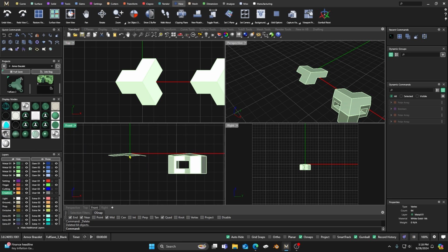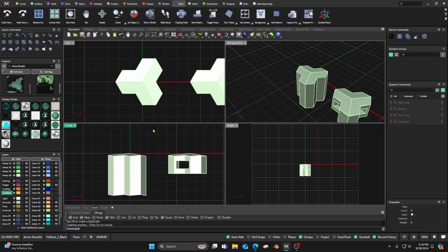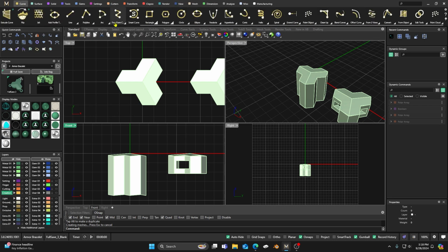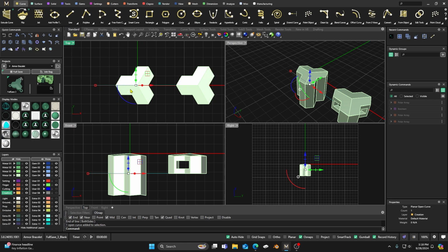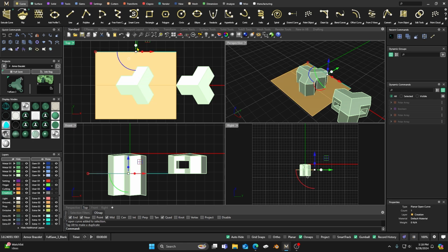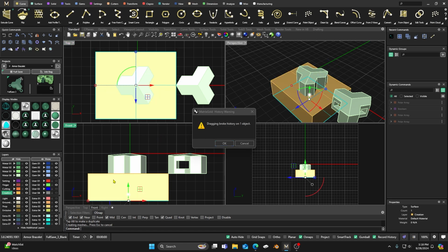All right, so we just have this top piece here, these three top pieces, and then this item for a reference, right? Now I'm just going to take all this and extrude it down. And then I'll grab me a line real quick and snap it with my snaps on from right there, that edge there, and just hold down shift and draw it over. Then I'll grab it, hold down shift and grab my little gumball with the little ball and extrude it to both sides, right? So I have that. Then I'll select it and drag it down like that there.